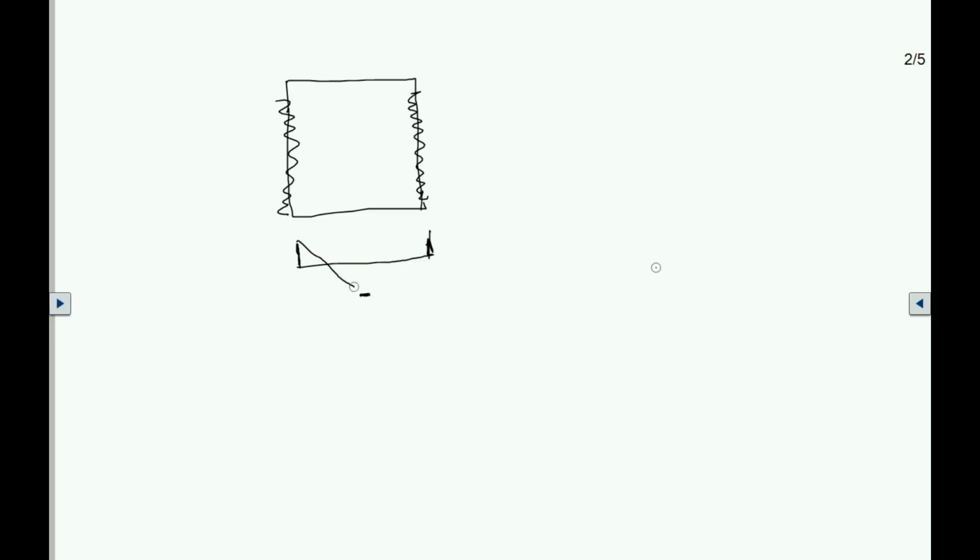So it will be somewhat like this. You need to calculate the negative moment here, here and here, and for that we need alpha x and alpha y. In this case there will be Mx positive and Mx negative.